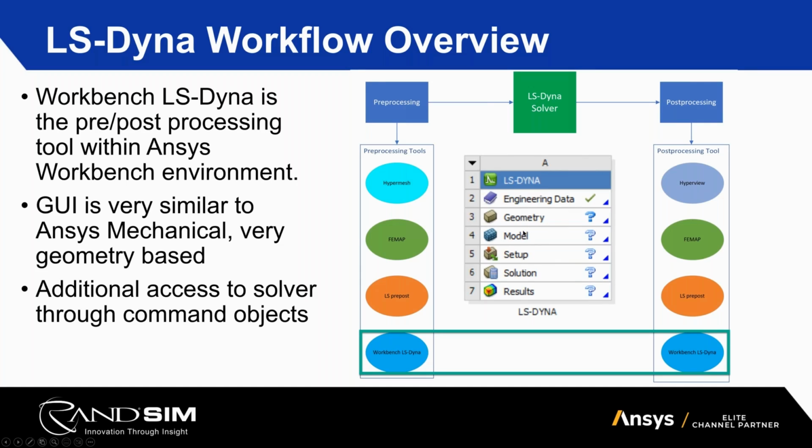It has your geometry prep tool in your model, similar to any Ansys Mechanical model. And this is a tool that's very much similar to a typical Ansys preprocessor, right? But its goal is to create the input deck, which is going to be read by the solver, and it also has the capability to post-process information that's being written by the solver, right?